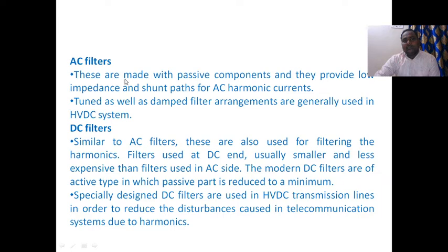AC filters are made with passive components, meaning inductive and capacitive components, and they provide low impedance shunt paths for AC harmonic currents. Tuned as well as damped filter arrangements are generally used in HVDC systems. Normally tuned filters and damped filters.